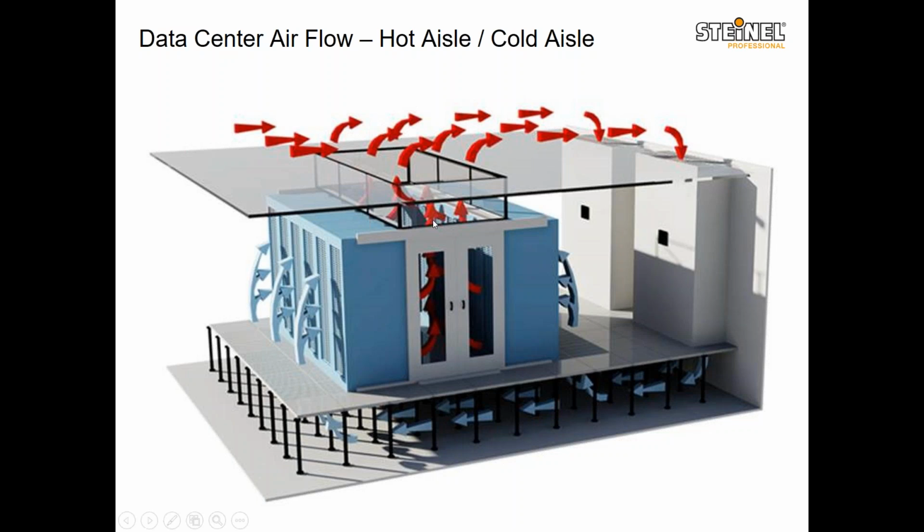And then the air goes into the cool aisle. The cool aisle is often also sealed, and it'll have access ports at either end, and those are sealed doors. And so you have to treat both of these areas slightly differently in your design because one of the areas is completely sealed off, and the other has access for people to walk all the way around. The normal people access is always in the cool area, and then the specialty access is within the hot aisles.